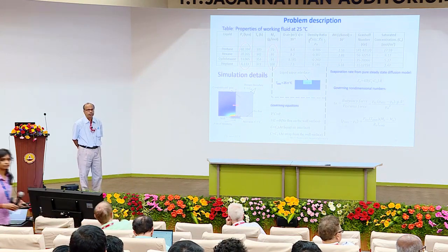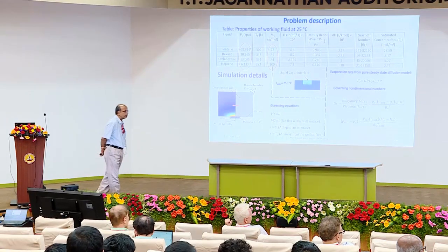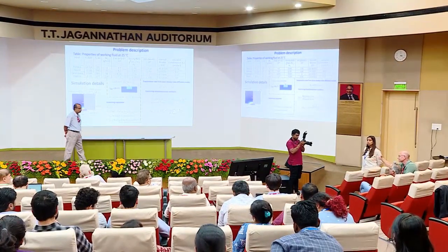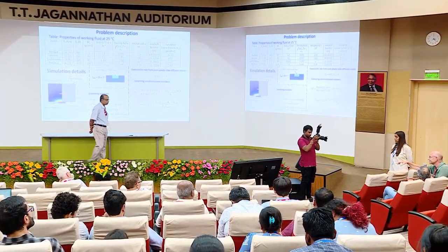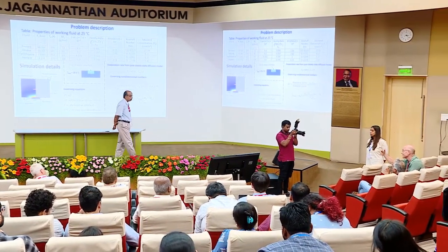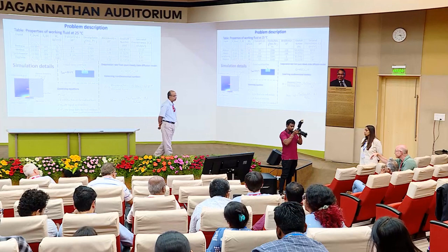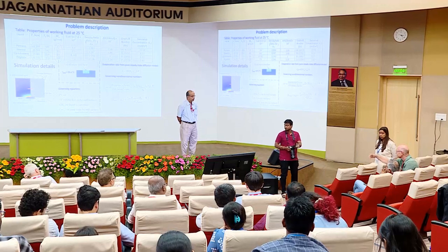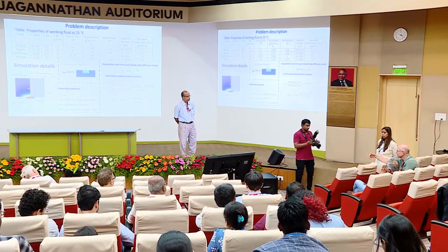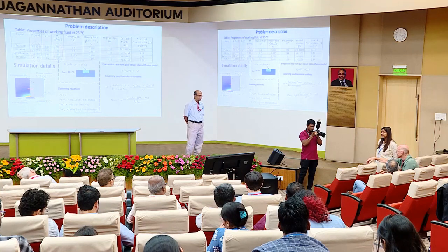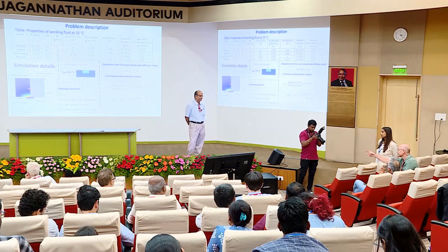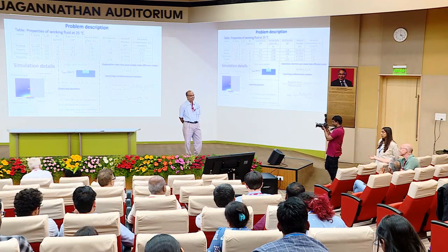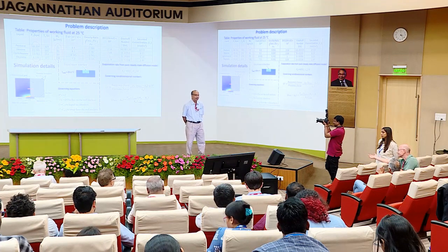Okay, I have a nasty question on methodology. You use the Mach-Zehnder interferometer, and as always you get the integral line-of-sight density differences, but you don't want that, so you use either tomography or onion skin decomposition. Then you get absolute density changes and you have to take the gradient, which is what you want. So why didn't you go directly with a Schlieren that gives you the gradient, and then a focusing Schlieren, so you would have only one two-dimensional plane? A focusing Schlieren would be the natural thing I would do. My question is, why didn't you do that?